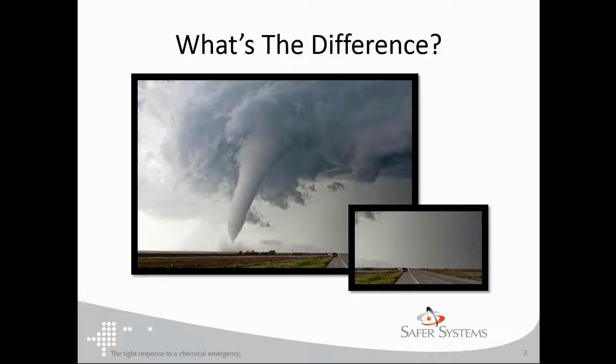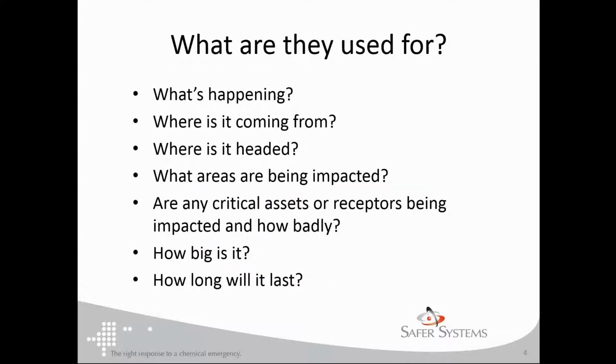So for gas detection data, again, static data is obtained through various measurement techniques, things that provide static data like a pull tube where you're not continuously monitoring but just taking a sample, or a gas chromatograph, or any online analyzer that's taking samples every X time period. So the data is static because you obtain the data as requested, and really we're serving here with online gas detection or continuous gas detection to be able to provide a better picture or the full picture of what's happening over an instance or a period of time.